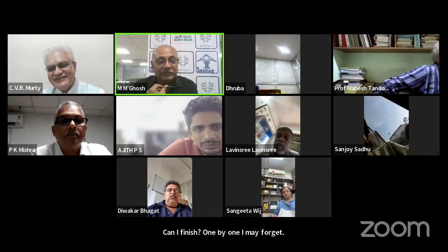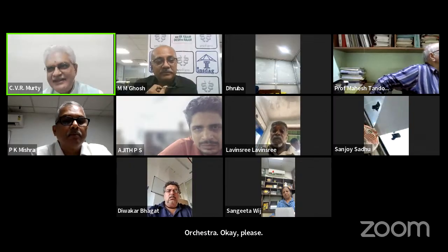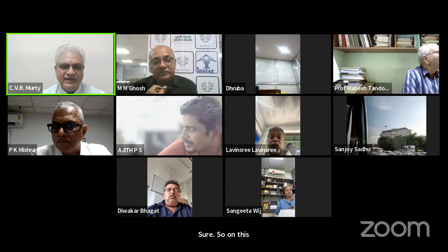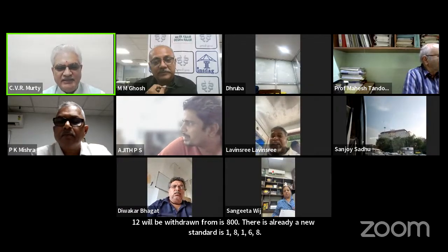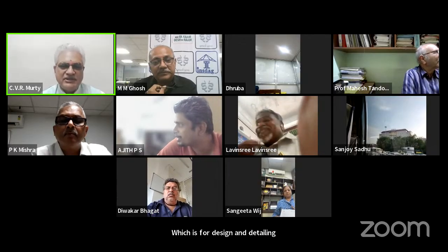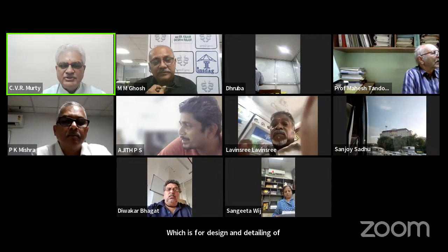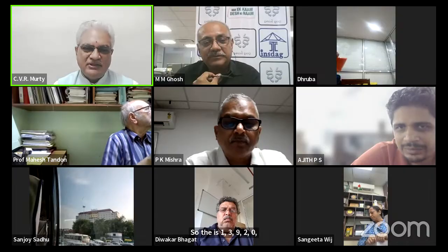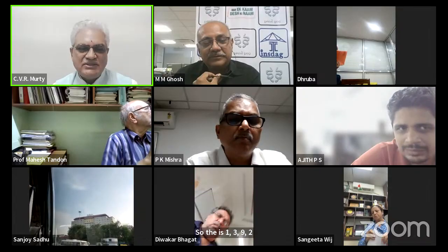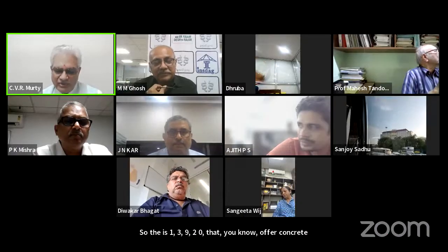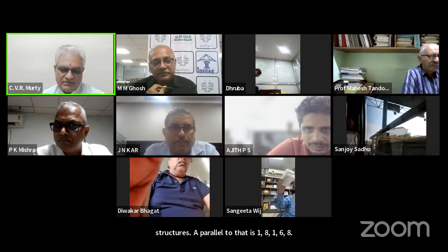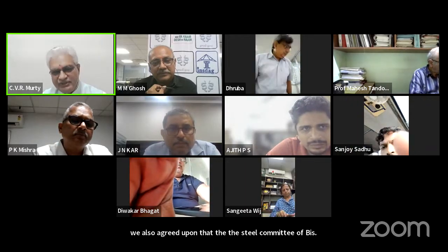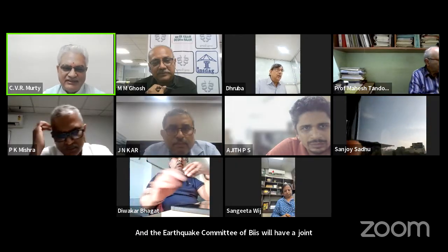Okay, please. Sure. On this thought, the good news is that chapter 12 will be withdrawn from IS 800. There is already a new standard, IS 18168, which is for design and detailing of steel buildings which are meant for earthquake safety. So the IS 13920 that you know of for concrete structures, a parallel to that is IS 18168. And we also agreed that the Steel Committee of BIS and the Earthquake Committee of BIS will have a joint working group for all future revisions that we will undertake.